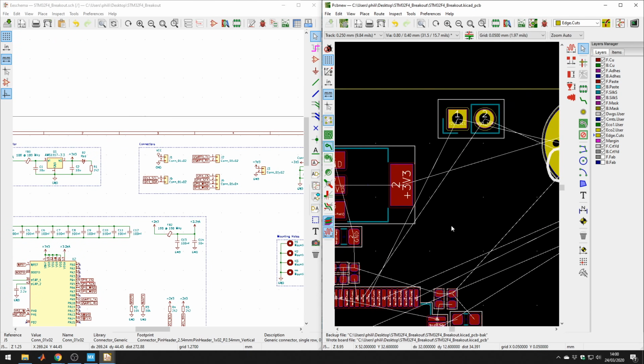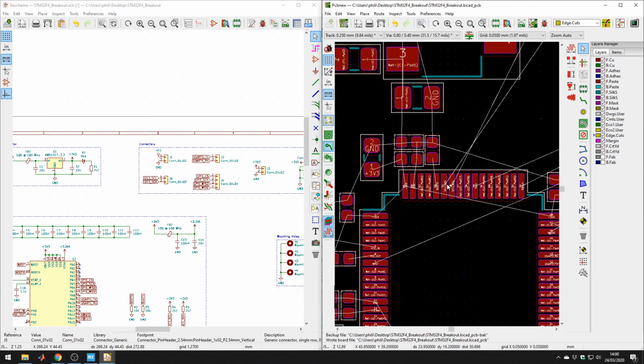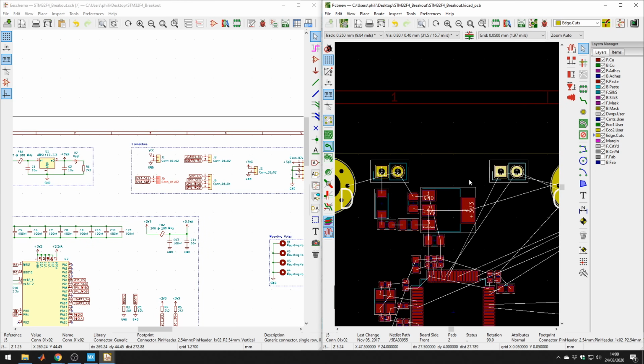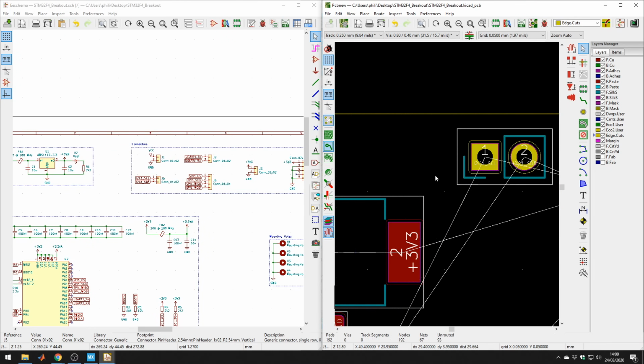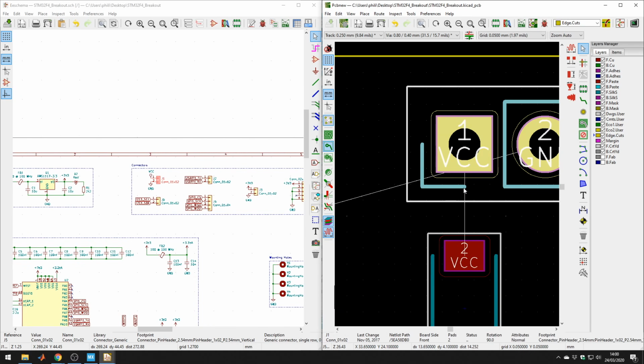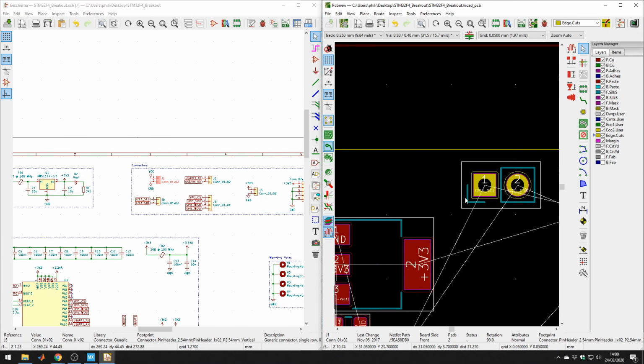Okay, and what this means, because we put down our SCL and SDA connections, actually they're crossed over, aren't they? See, here's a case where I would change something in the schematic. Because of, well, purely aesthetic reasons, you always have this one indicator on the silkscreen, this little right angle, and I want that always facing up, so to speak.